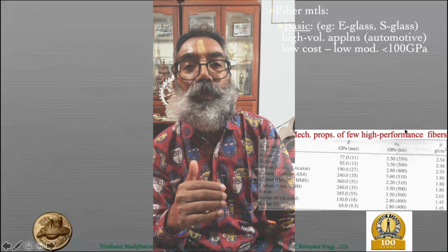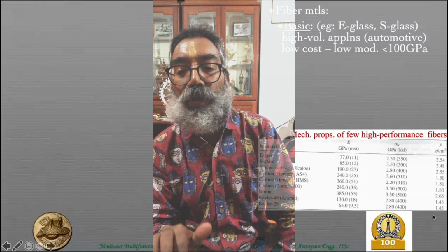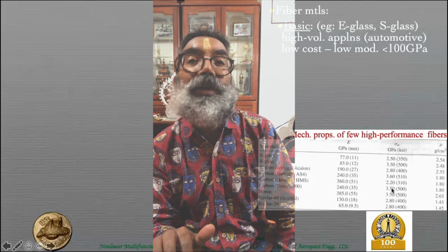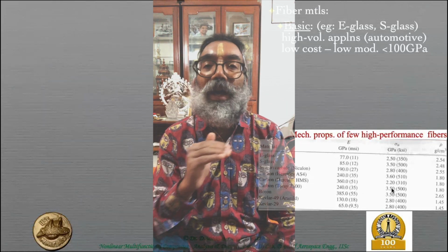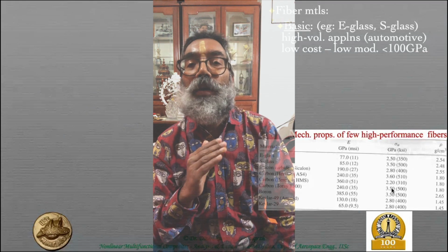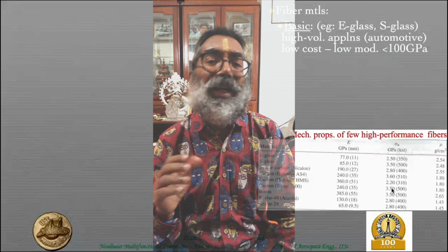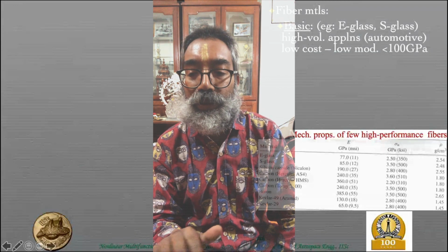Glad that you brought that point out, because it doesn't come purely from Young's modulus or the ultimate tensile strength or rho, but from a higher failure strain, so it should have a certain plastic regime where it goes through a yield kind of situation, may not be exactly yielding in a metallic sense, but in a certain sense like that.